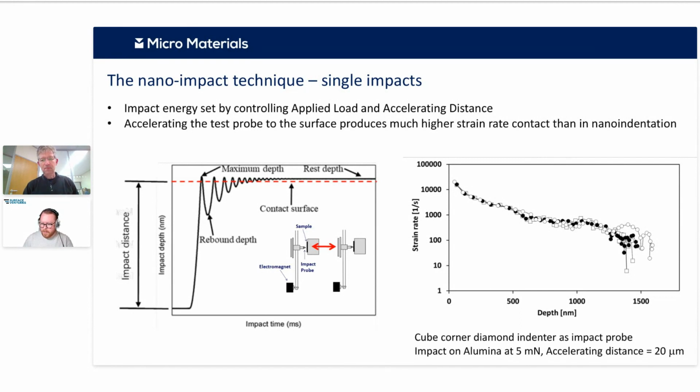Got it. I think we'll take what will be the final question here from Sankara, who asks, "Is poor adhesion a reflection of the integrity of the base coat or the top layer?" Well, in the example I showed right at the end, it's a multi-layer optical coating system, essentially, and the poor adhesion in that case was caused by an ineffective plasma treatment.